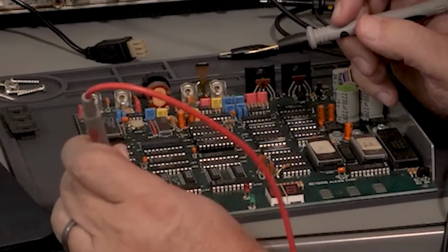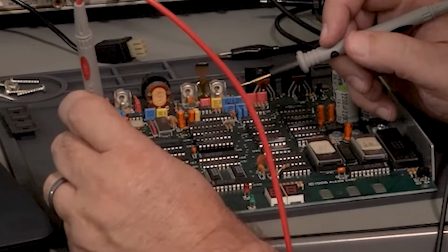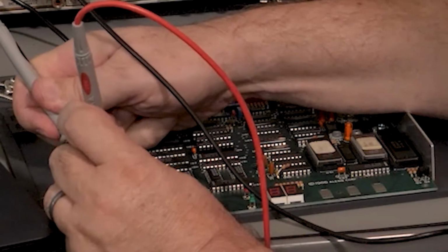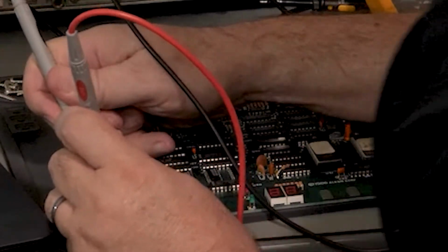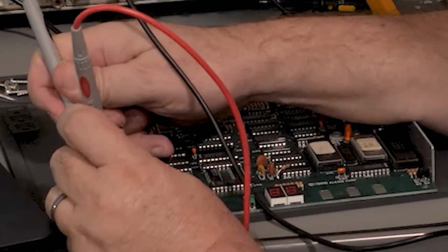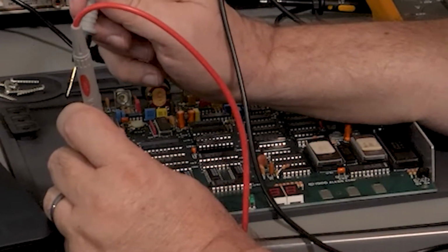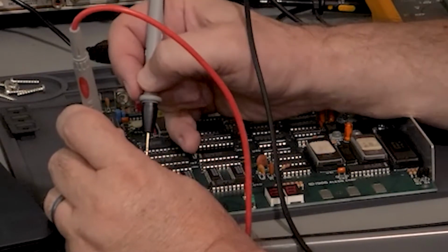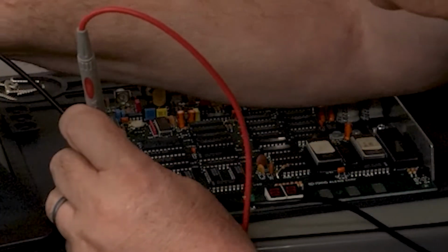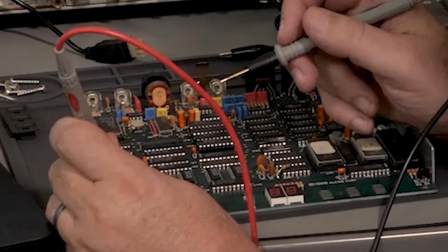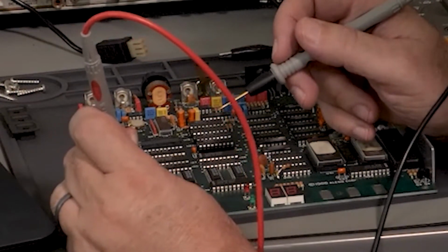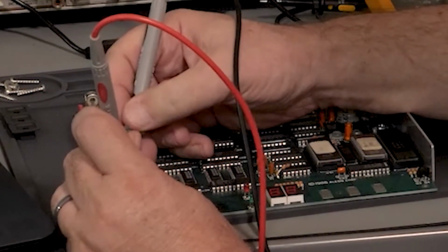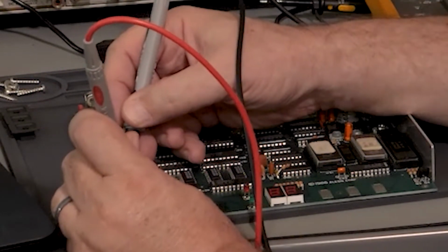So let's look over here at pin 2, and let's see if my theory is right. I'm going to rake it across this adder, and sure enough, it's on pin 2. Is it anywhere else? Anybody else have it? No, I don't expect it to. What's the next output? All right, it's on pin 5. 1, 2, 3, 4, 5. Right there. Do some raking. Not over there. Oh, it's right there on that adder.